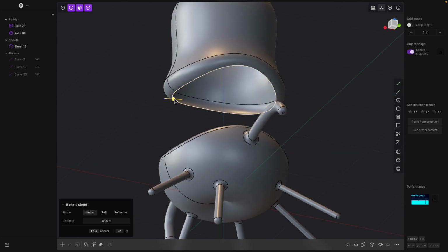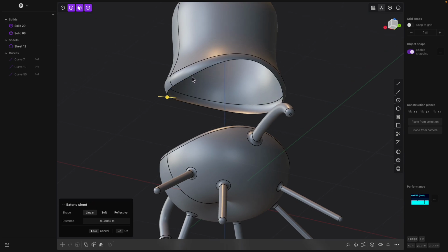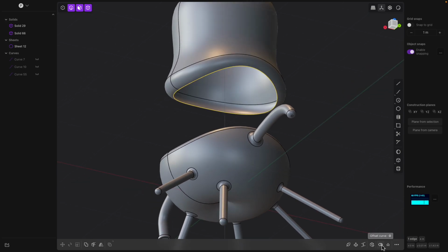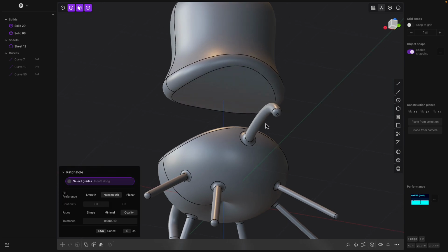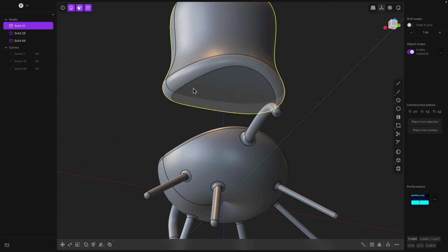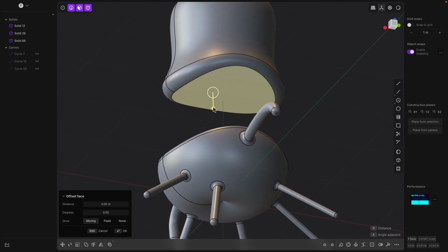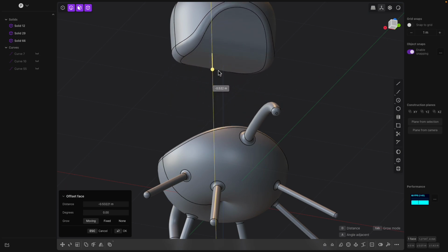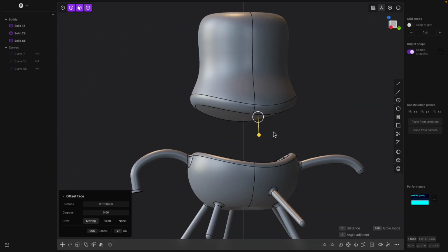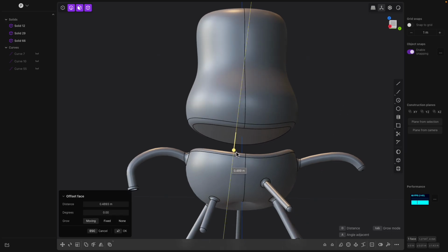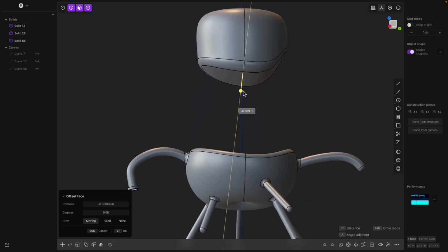Yeah, you might want to do that, but in this case, if you have something hollow, it's becoming a different object, like a sheet object. It's no longer solid. But if you select this face again and we patch the holes along edges, boom, it becomes solid again. Parasolid, I like it as a Parasolid because we can do fancy stuff. It seems to remember the original shape, sort of.